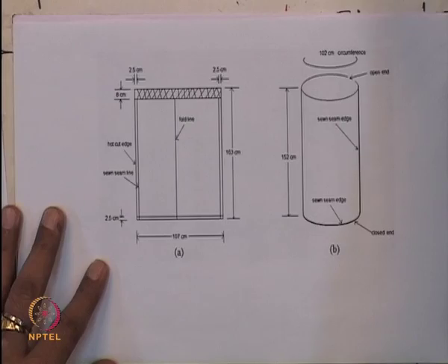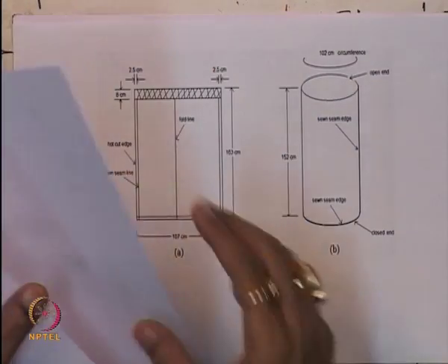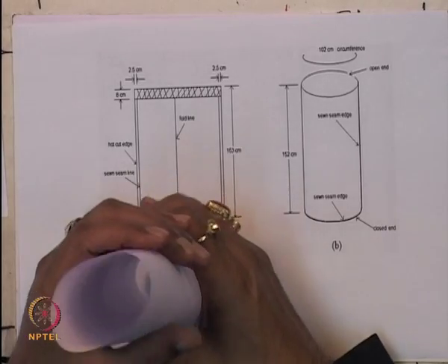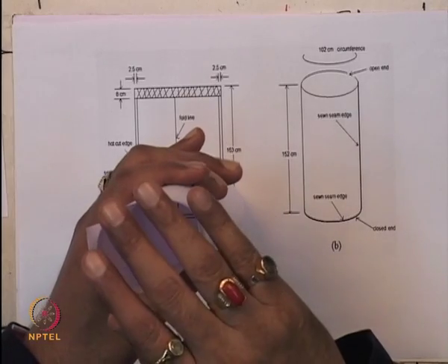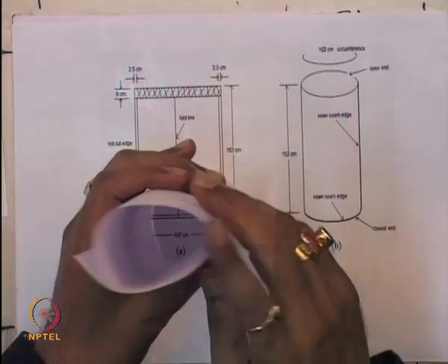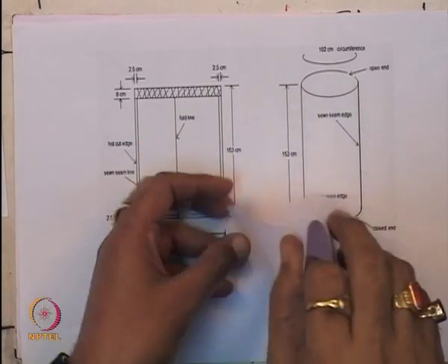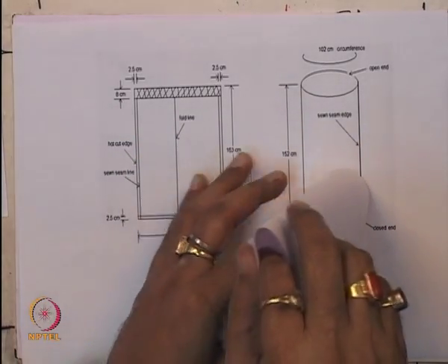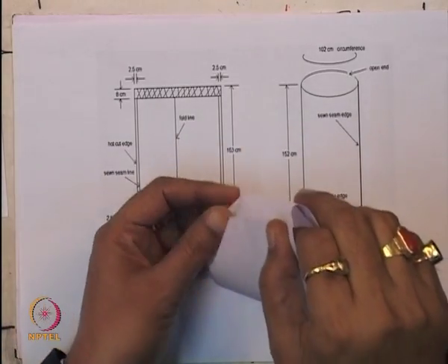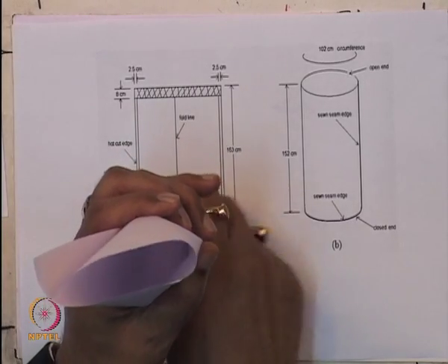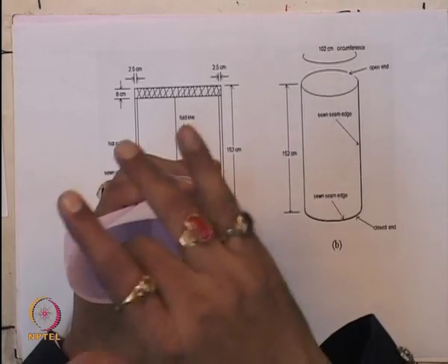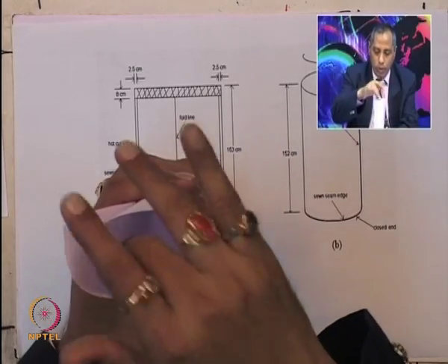So it is a fabric made of polyester woven or jute geotextile material, cylindrical in shape. So this is either the jute geotextile or the woven polyester geotextile, and this part has been sewn, this side also sewn, and butterfly stitching has been adopted, and the bottom part also has been sewn, and the slurry has to be inserted into this geotextile tube from the top.